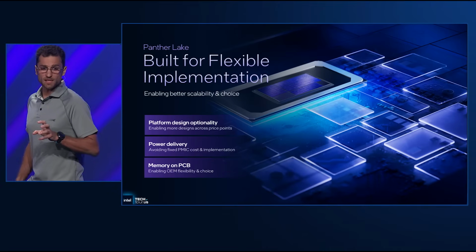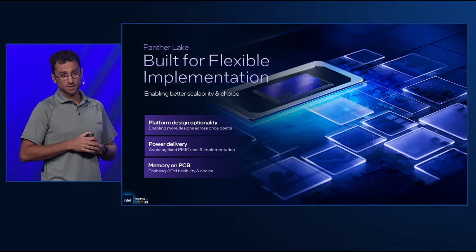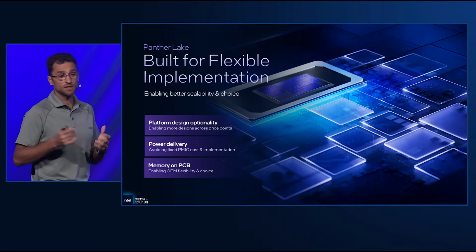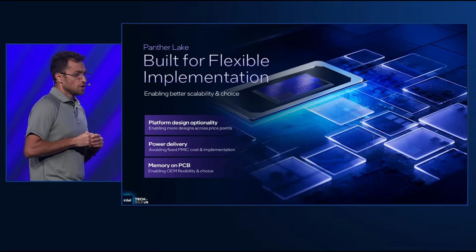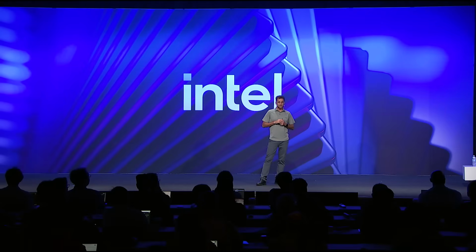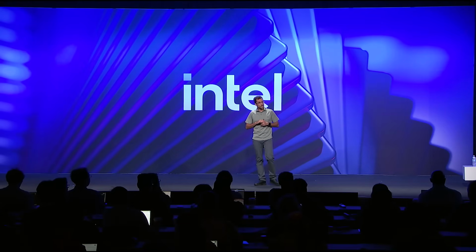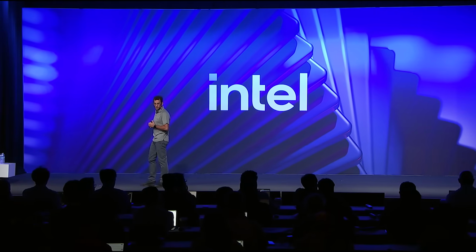To allow platform board flexibility and support a broader set of segments, while Lunar Lake invested in a dedicated PMIC for power delivery and also integrated memory on package, Panther Lake will allow platform design optionality. For power delivery, Panther Lake will unleash the use of higher currents with discrete VR topology to meet the engines' horsepower and a wider range of platforms. And for memory, with both LP5 and DDR5 support, OEMs can have the flexibility of selecting the right technology, speed, and capacity that fits the platform.